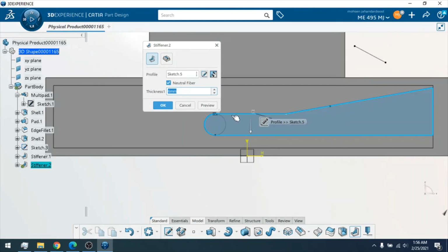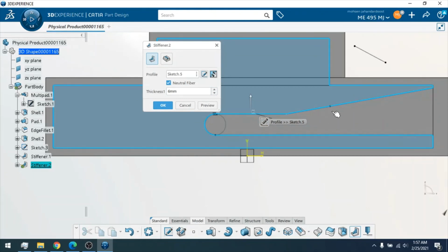So here I have my profile. The first thing is that it propagates parallel to the plane that I created, so it goes inside in this direction. And the next thing is that it follows the tangent to the line. So I finished here, and the profile follows the tangent to meet the boundary. And also for the circle here, you can see that I finished here, and it just follows the natural direction to meet another boundary.